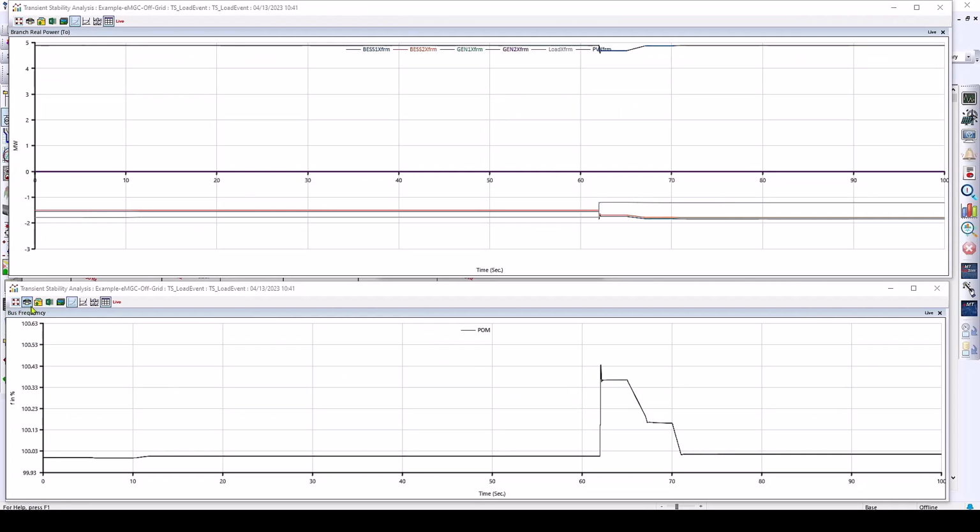In this scenario, at time 61 seconds, an event happened. This event is a load reduction event. So basically, when the load is reduced in the system, the other assets will react to that event. The PV is trying to reduce its generation, and the battery is trying to increase the discharging power. Through these remedial actions from the primary controller, we can see that the system frequency is not going very high, and they can limit it to 100.4%. However, this frequency is still too large, and we need to reduce it. The microgrid controller is executed every 5 seconds.